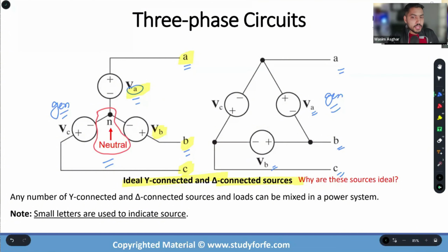And if I tell you that there is actually a neutral over here in delta as well, you're going to say, Wasim, I cannot see it. Neither can I. But the fact of the matter is that this neutral, geometrically at least, does exist and it is inaccessible. We cannot access it. When we discuss single line to ground fault, and go into details around why a single line to ground fault on an ungrounded system does not result in activation of overcurrent protective devices, and we create the phasor diagrams, we actually work with a neutral reference in order to fully understand it. But let's leave it aside and understand that in a delta network, you don't have an accessible neutral.